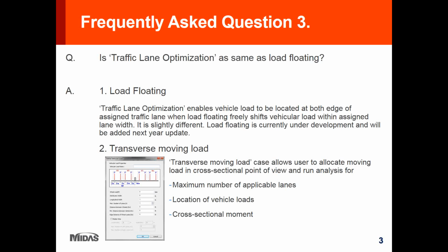Load floating is literally shifting the vehicle load along the lane width, while traffic lane optimization only allocates the applied vehicle load on each edge and the center of the applied lane width.